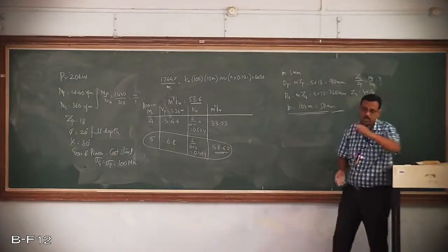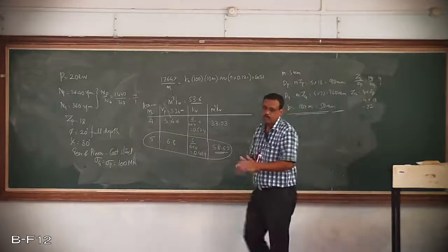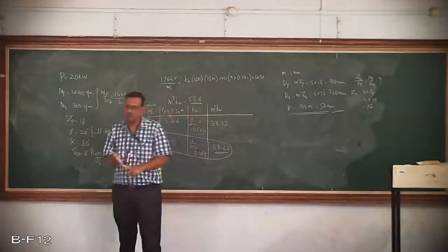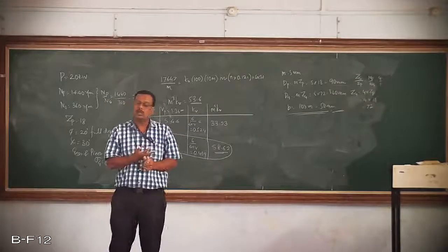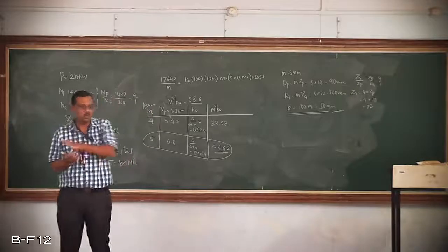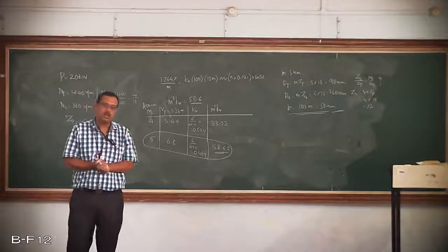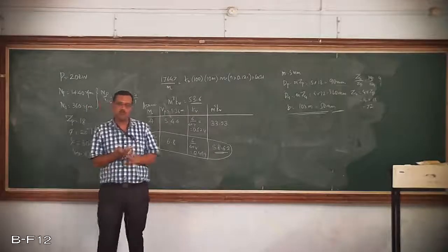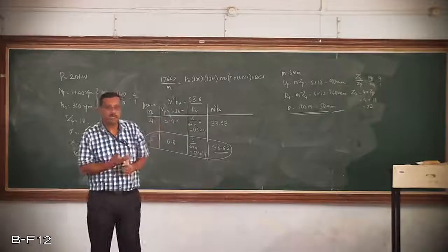If you have difficulty, you can revert back and inform. And just to wind up, today we have gone through, in brief and very quickly, the equations to be used for the design of helical gears. The first problem is solved based on the design of helical gear, that is power transmitting capacity. In that case, all the dimensions of the gears are known to us. We need to determine the value of tangential load. If you know tangential load, you know the velocity. W into velocity gives the power transmitting capacity of the gear.